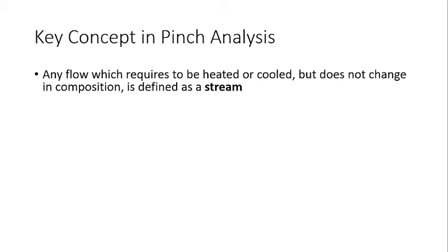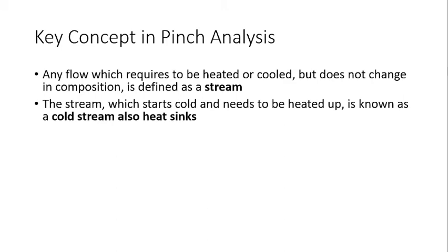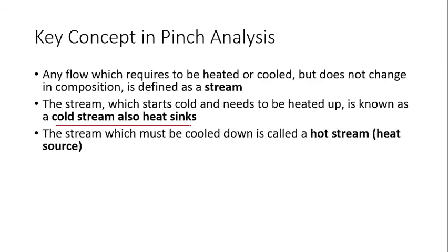Let us talk about some key concepts in pinch analysis, and then I think we'll call it a day for this particular session. Any flow which requires to be heated or cooled but does not change in composition is defined as a stream. So this is a process stream. Either the stream requires heating or it is cooling, but it's not changing its composition. The stream which starts cold and needs to be heated up is known as a cold stream or heat sink. The stream which must be cooled down is called a hot stream, a heat source.